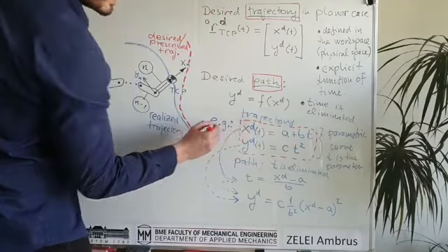So if the arm is totally bent, so Q2 is equal to pi, 180 degrees, the tool center point will be somewhere here, and there will be a smaller circle of the radius which equals the difference of the bar lengths in absolute value. So you cannot reach the origin if the lengths are different, right?